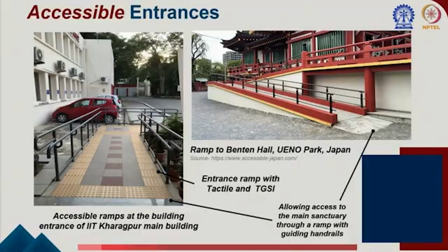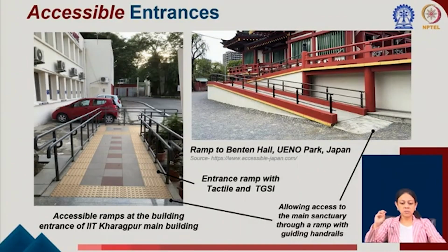These are some examples of an entrance ramp. One challenge in providing ramps to the entry of a building could be maintaining the adequate slope when the level difference is considerably large. If you have something as simple as a straight ramp, you can have it easily. But when you have something like this, you might need to turn the ramp so that the entry level can be accessed.